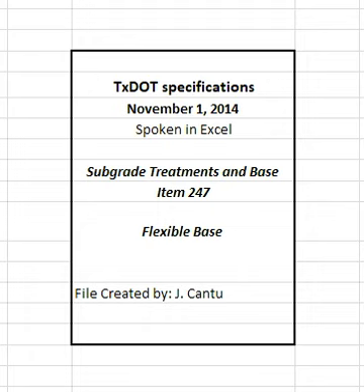4. Construction. Construct each layer uniformly, free of loose or segregated areas, and with the required density and moisture content. Provide a smooth surface that conforms to the typical sections, lines, and grades shown on the plans or as directed. Stockpile base material temporarily at an approved location before delivery to the roadway. Build stockpiles in layers no greater than 2 feet thick. Stockpiles must have a total height between 10 and 16 feet unless otherwise approved. After construction and acceptance of the stockpile, loading from the stockpile for delivery is allowed.